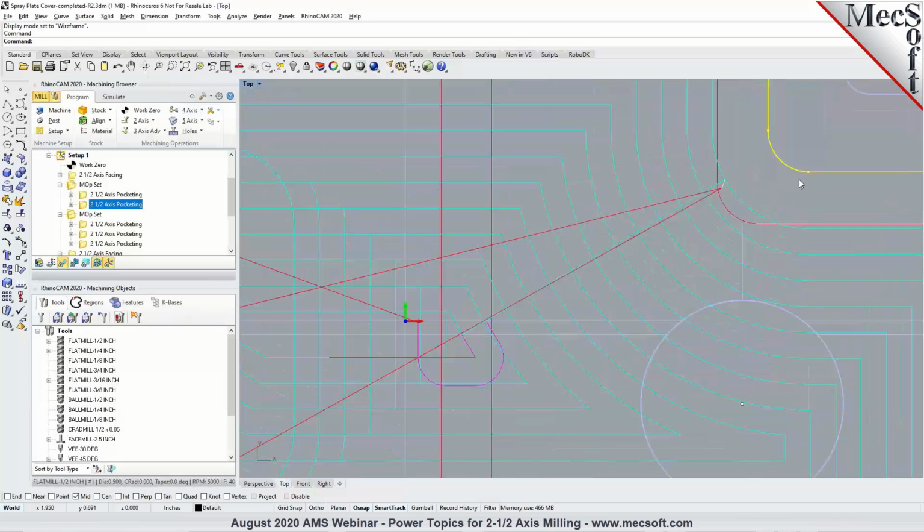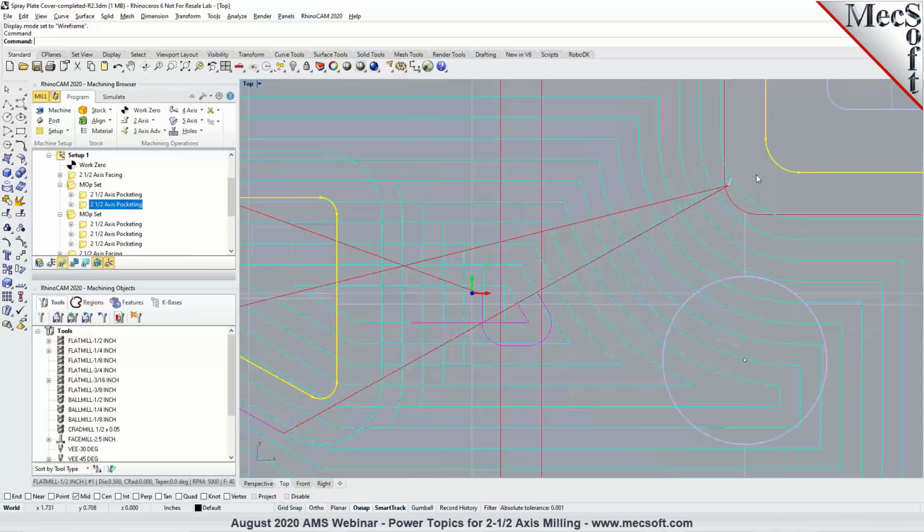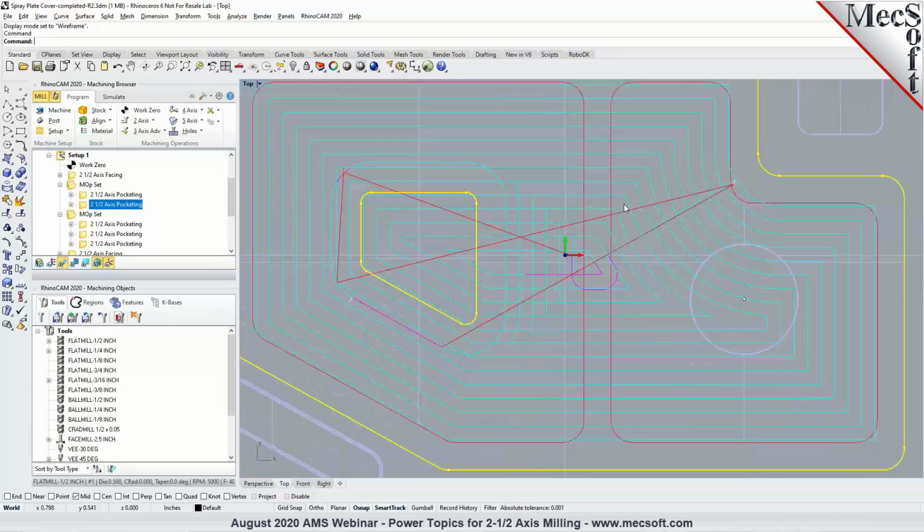So tightening it up to 1,000, well, you can see that there are smaller facets and much tighter, much closer within the tolerance of the part region of the geometry for both the pocket boundary as well as the island region. Now the same goes with the other two.